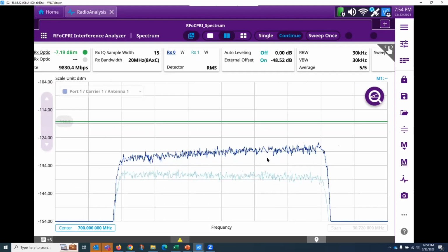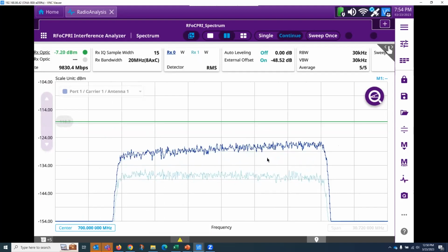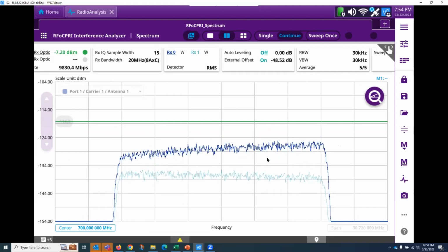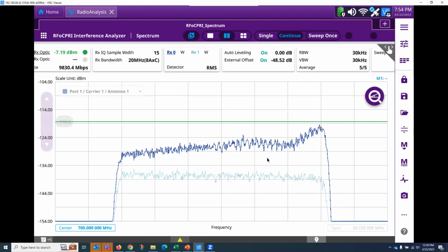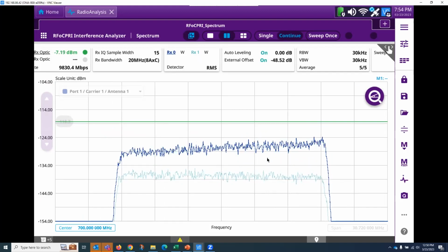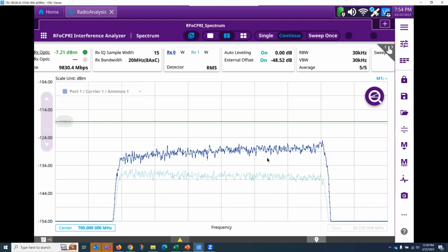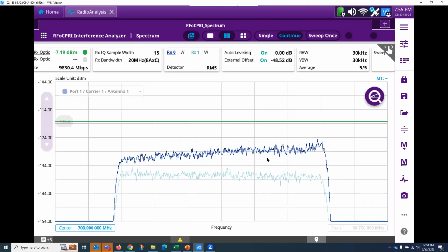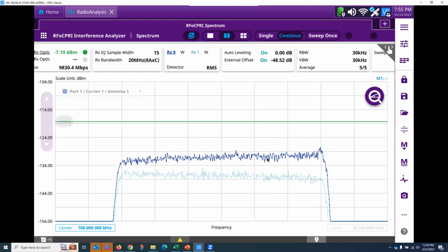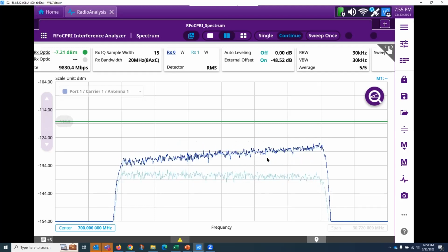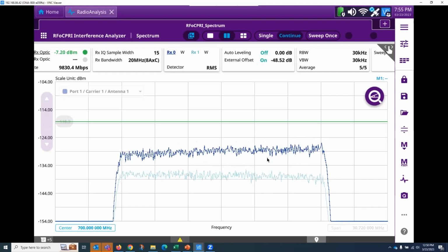It is not 100%, but you can allude to that because on the other side, when it's an external problem, it almost always affects at least 2 branches. If you think about how branches are, antenna 1 and 3 are usually the same polarization, plus 45, for example, and 2 and 4 are going to be the negative 45. The 2 positives at a minimum should get affected. I know there are people out there who are going to say no, and that's true because there's always a gray area here, but that's the easiest way to figure it out.